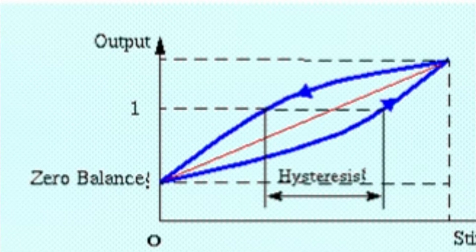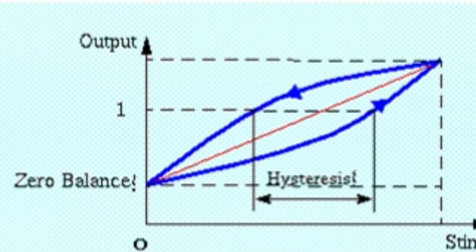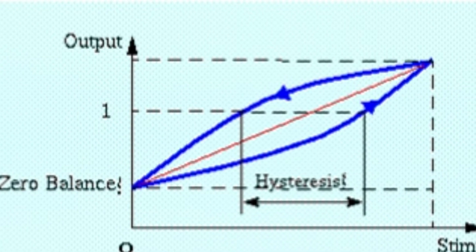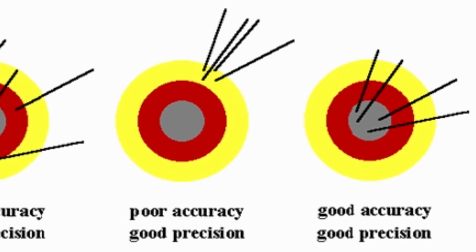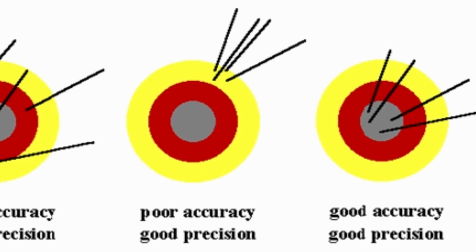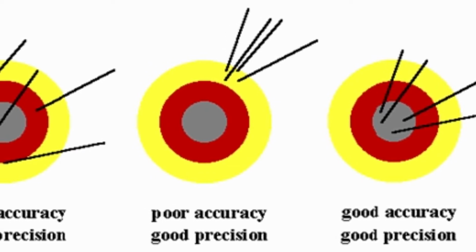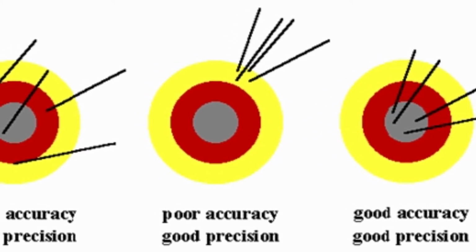Response and recovery time. The response time is the time taken by the sensor for its output to reach 95% of its final value when it is exposed to a target material. The recovery time is defined conversely.